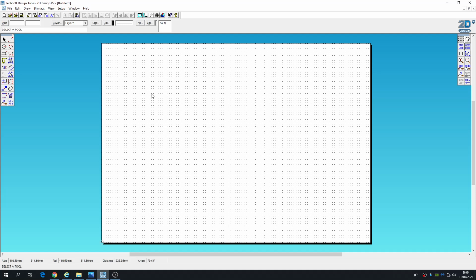Now, depending on what you're doing, if you know the drawing sizes, you might decide that what you're making is easily divisible by 4, in which case you could set your grid spacing to 4mm instead of 5mm. So that's a 5mm grid at the moment, which is what I did in the previous dialog box.